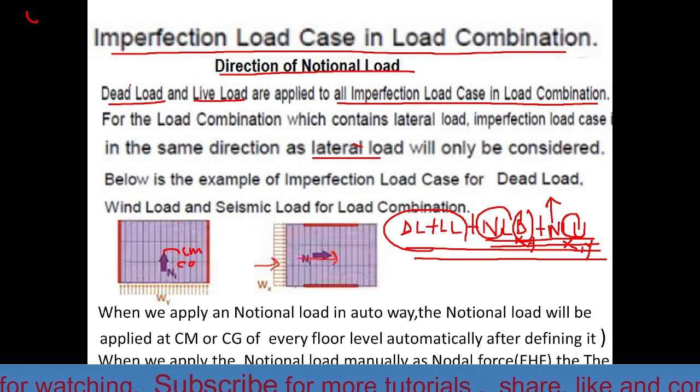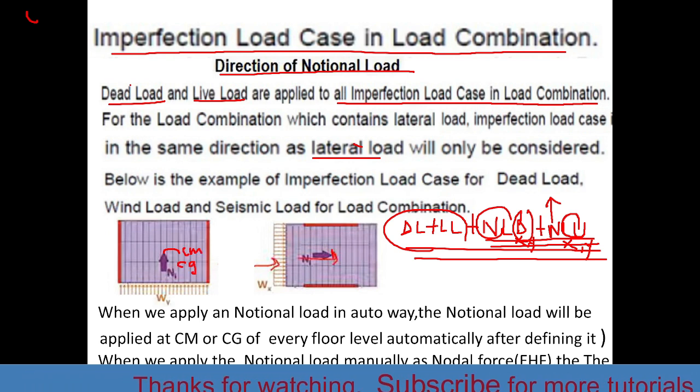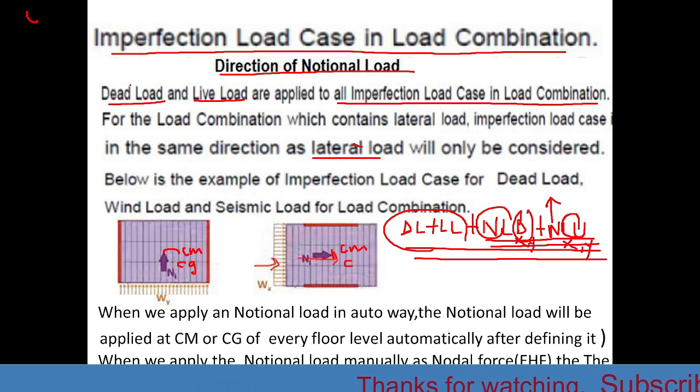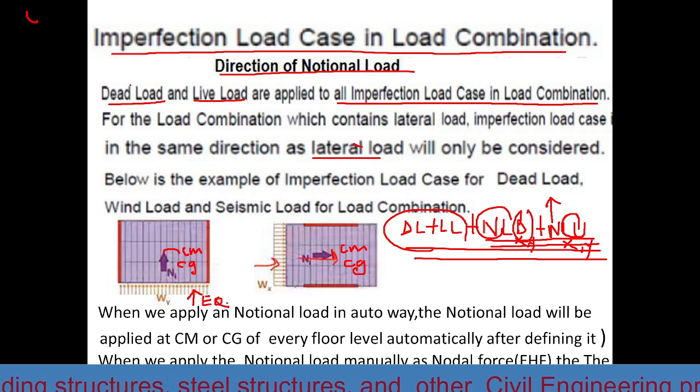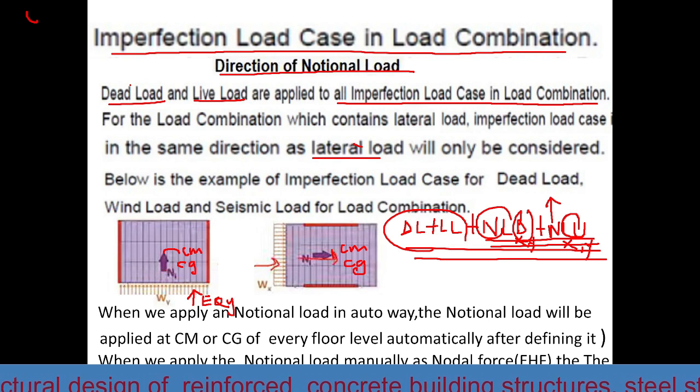Or at center of gravity. Here, center of mass or center of gravity. So, if we also apply the seismic load, that means earthquake load EQY in this direction, the notional load has to be applied along the y direction.